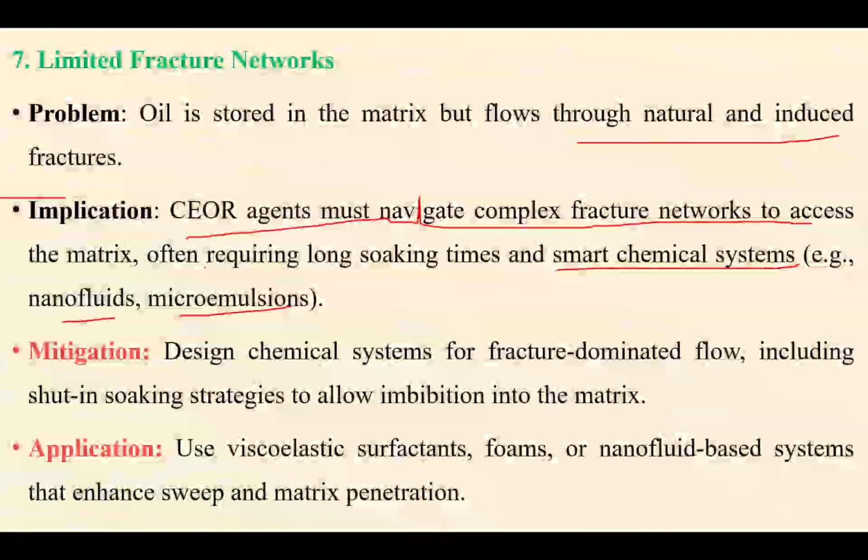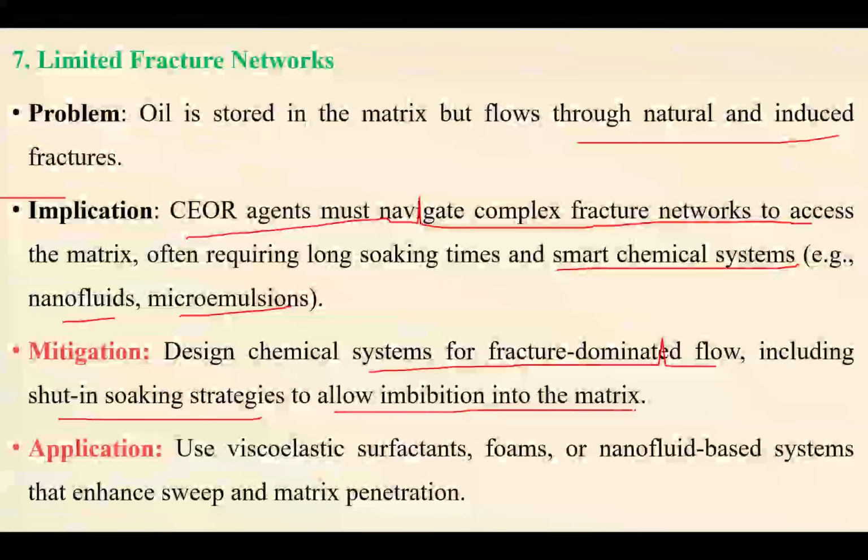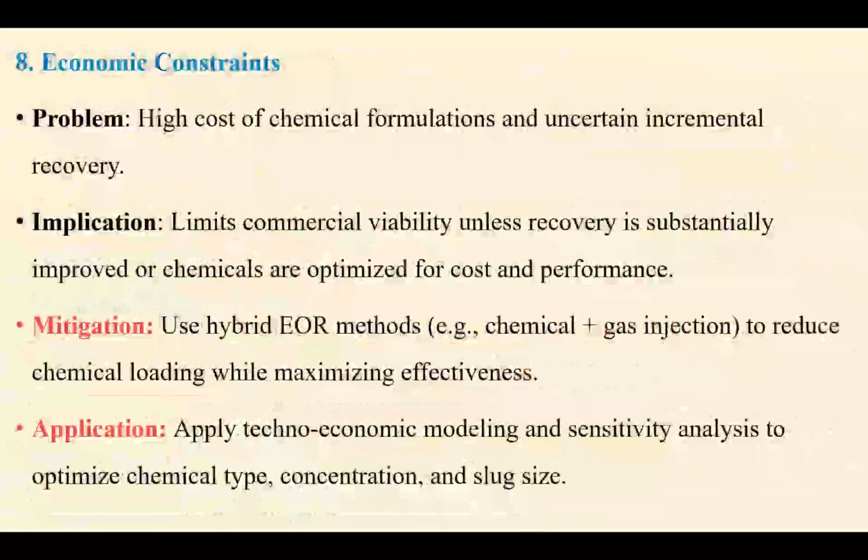So the mitigation is design of chemical systems for fracture-dominated flow, including a soaking strategy to allow imbibition into the matrix. Sometimes we can go for profile modification also. And sometimes viscoelastic surfactants, foams, and nanofluid-based systems can enhance the sweep and matrix penetration.